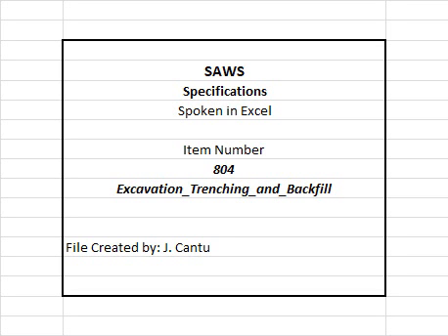Rock or stones having a dimension larger than 6 inches at the largest dimension shall be sifted out and removed before the material is used in the secondary backfilling zone. 2. Secondary backfill material shall be primarily composed of compactable soil materials. The secondary backfill material shall be placed in maximum 12-inch loose lifts or as directed by the engineer and/or inspector. Secondary backfill shall be constructed in accordance with details shown in the construction documents.